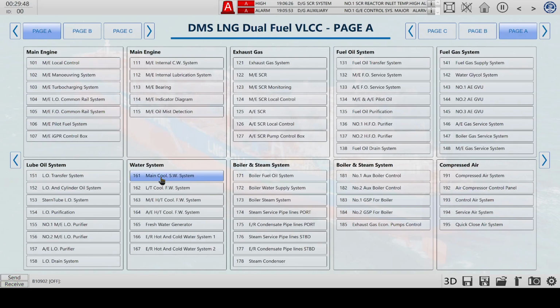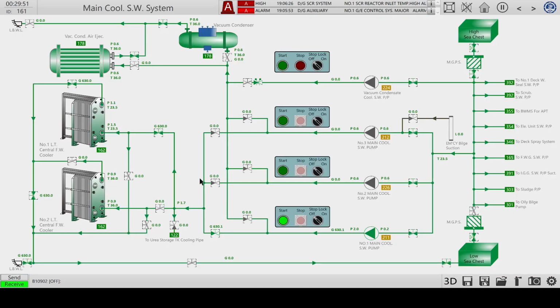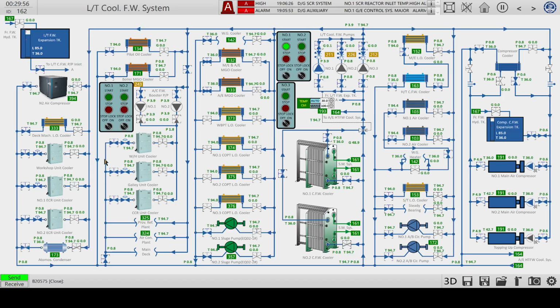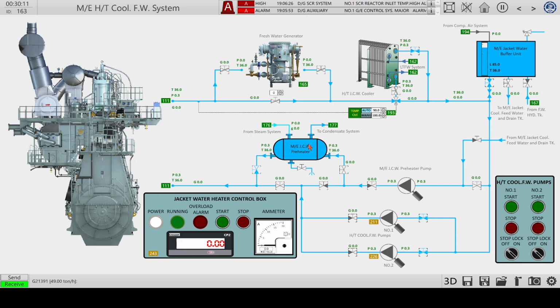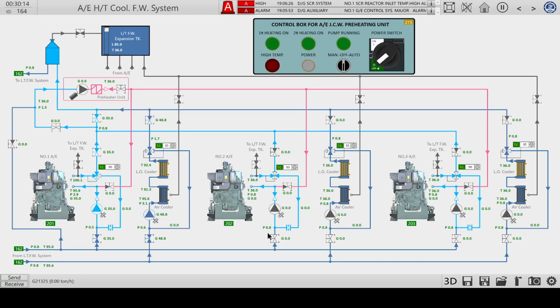Okay, let's go to the fresh water systems. Just to verify the seawater is still okay. Freshwater cooling is running okay. This valve doesn't have any use at the moment because we don't have the compressed air to use it. Let's just set up the other generators, so that if they go online automatically, they do have the necessary cooling. I think that's it. Those go to that line. Yep.